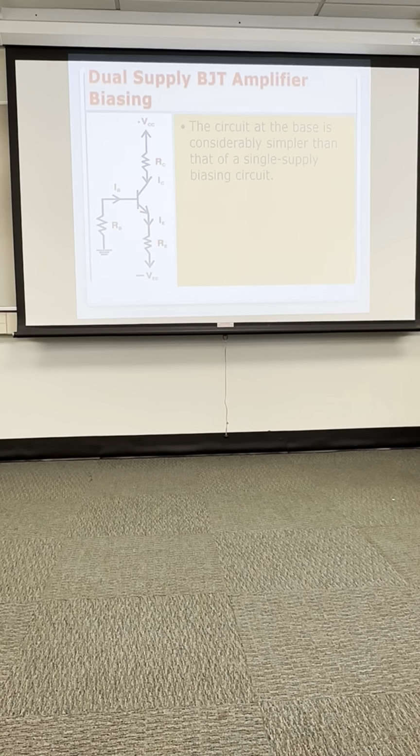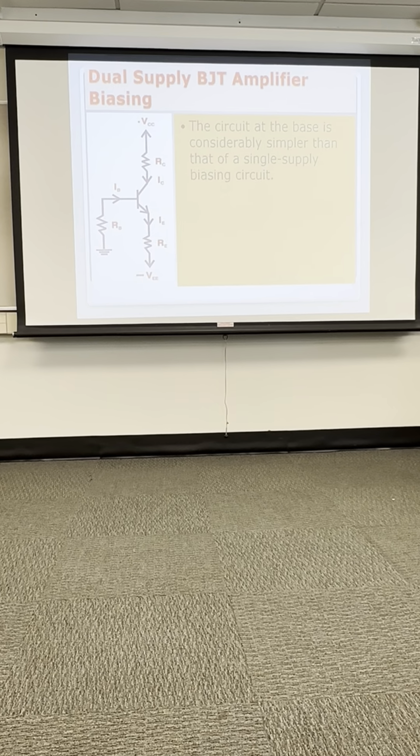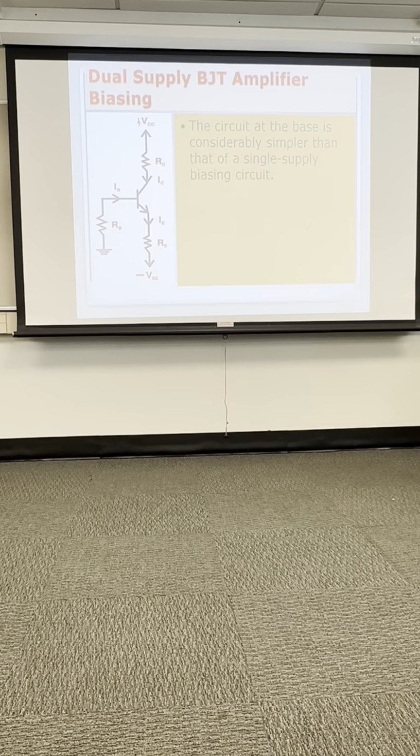Now this note here is just indicating that this amplifier will operate with 2 power supplies. These come in bigger amplifiers. We have a plus battery and a negative battery, and then we can tie the base resistance directly to ground here.